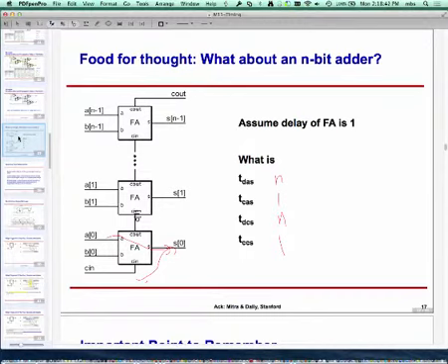The value of interest is the fastest the output will change, not the fastest under some condition across the range of parts. When you buy parts, the data sheet says its minimum propagation delay is this, its maximum propagation delay is this. What it is saying is that across the parts you buy, across different operating conditions, sometimes the propagation delay may be, let's say, 10, sometimes it may be 12.